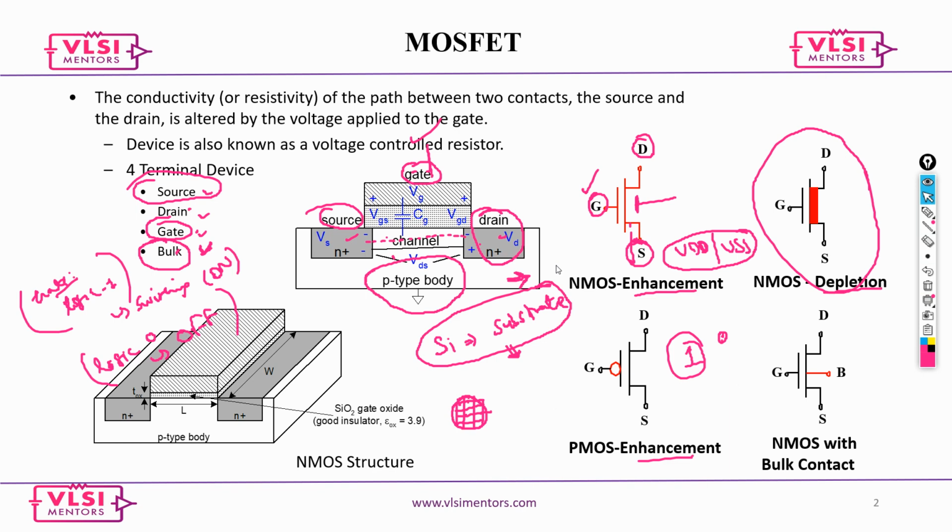It will be from a power consumption perspective that we choose enhancement, whereas depletion is always on, it will take power. Okay, I got what you're saying. These are all the basic understanding that you should have. You choose enhancement mode because whenever you want the transistor to switch, only at that time you turn it on, not the other way. Otherwise it is on all the time, and whenever you don't want it, you go and turn it off.